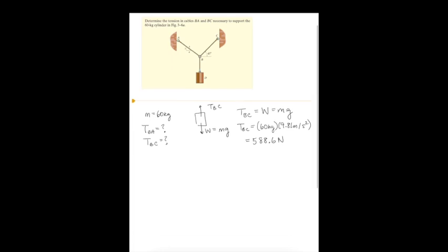But the real free body diagram that we need to draw is going to occur at the point B. So the connection at point B, we know that there's some force in the cord BC as well as in the cord BA. And we have this tension in the cord BD. We know that this is at a 45-degree angle, and we know that this goes over 4 for every 3 that it goes up. And we'll be able to use that information.